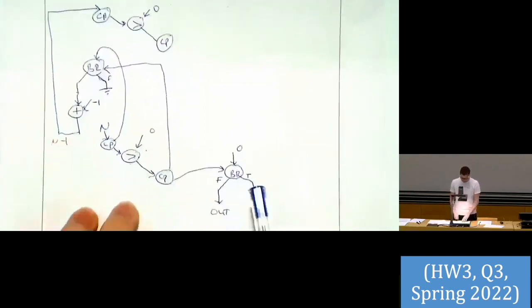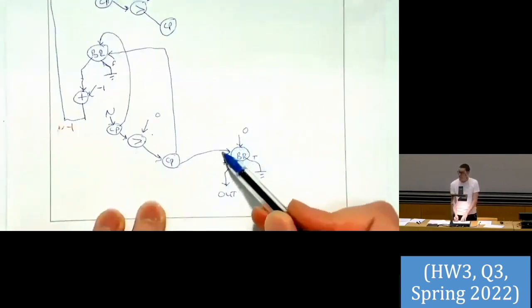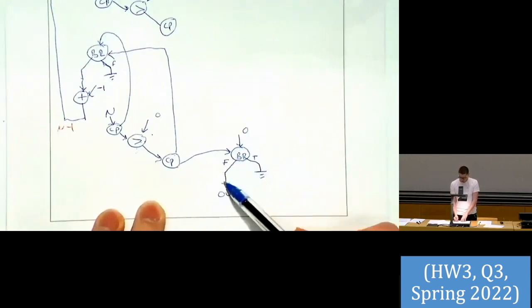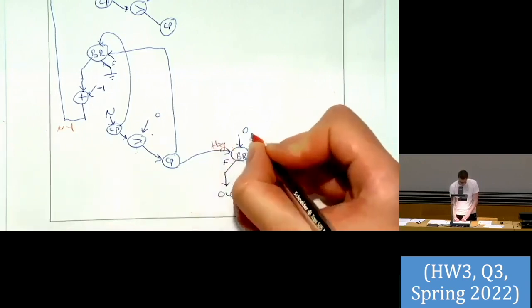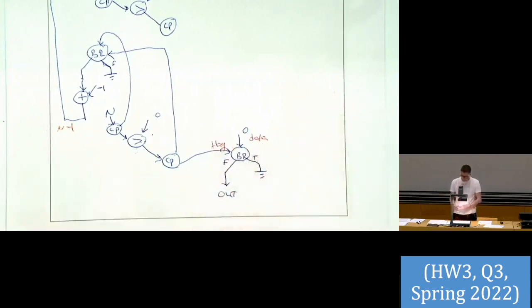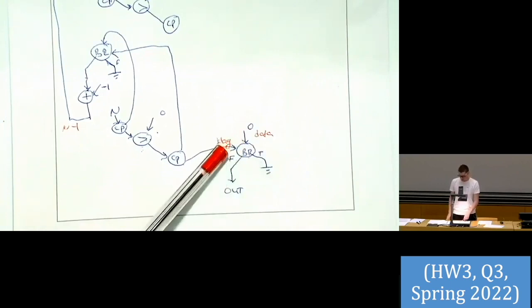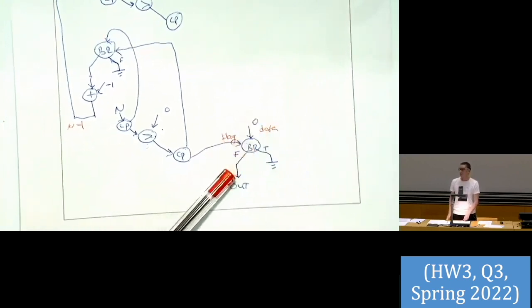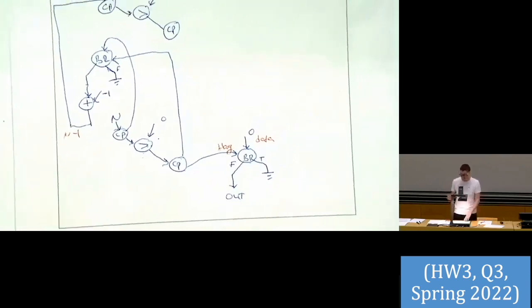Yeah, sure. So the branch node has two inputs, right? Both inputs should be valid, and it outputs either from the false path or the true path. One of the inputs is the flag, and one of the inputs is data. If the flag is true, the data goes to the true path. If the flag is false, the data goes to the false path. So the token is generated only on one of the output paths in the branch node. Is it clear? Okay.